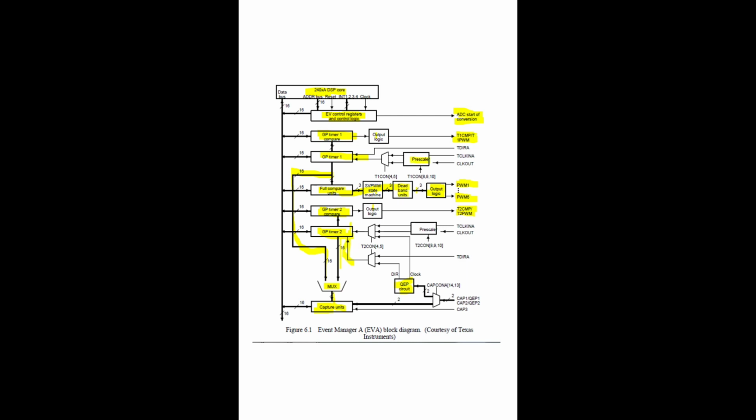Then here prescaler is there. Prescaler means whatever clock frequency you are giving to the processor, according to the work given to the processor, it will work. If you are not going to give multiple tasks to the DSP, then the DSP has no need to work quicker, because it has very little to do. It need not work at high speed, because if it works at high speed, obviously it will take more power, and that is unnecessary power wastage.